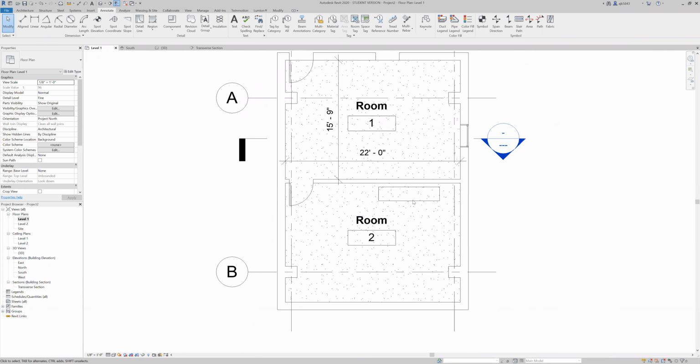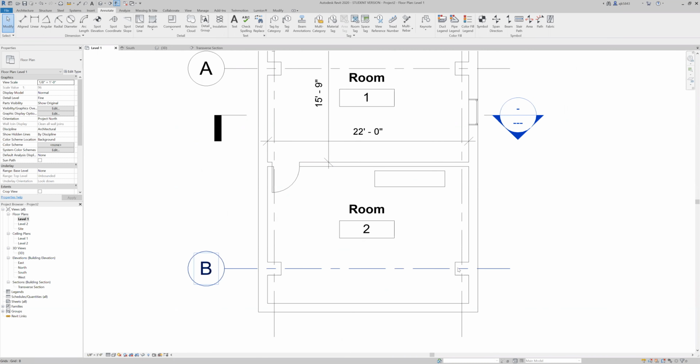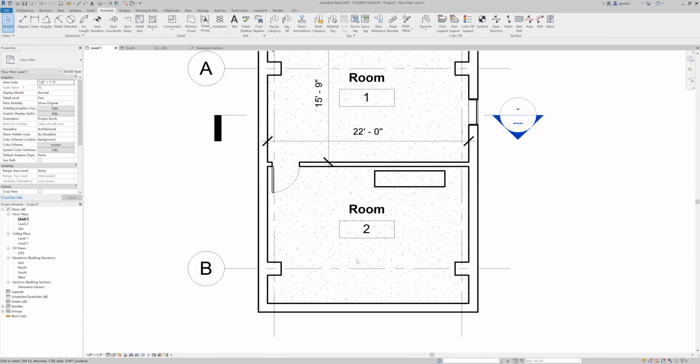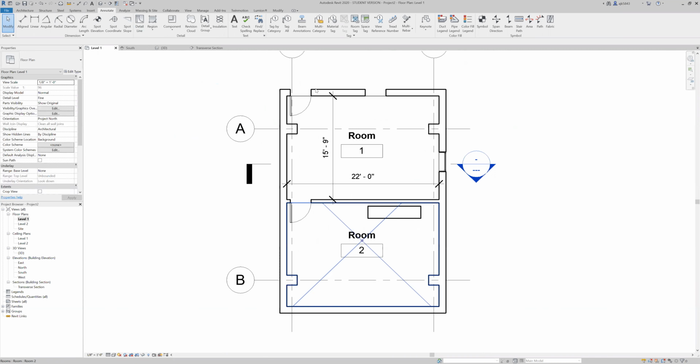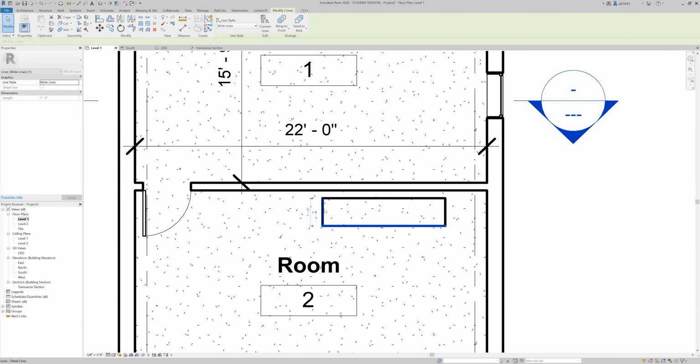So Revit has two different viewing modes, and it's right up here on the top bar. This is called thin lines. I always work with thin lines on because it's a great way to know exactly where you're placing your elements. But if you turn it off, you'll notice that you're going to get some heavier lines of where you're cutting through your geometries, as well as if you define a line as being heavier, such as in these detail lines.